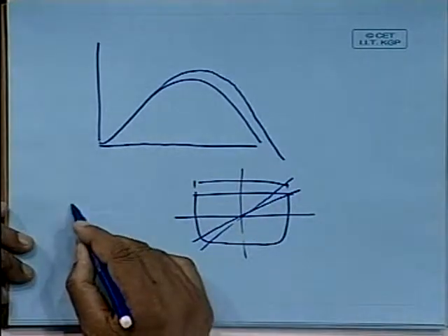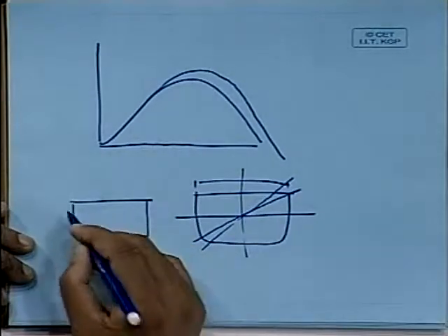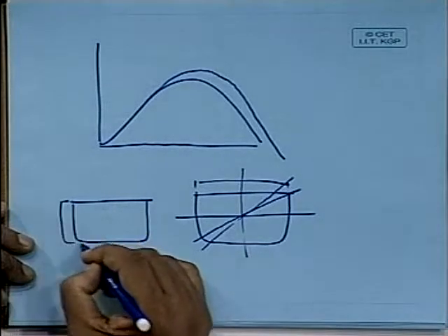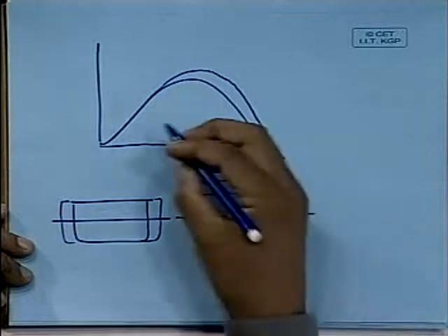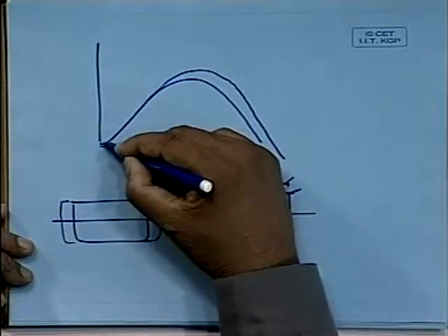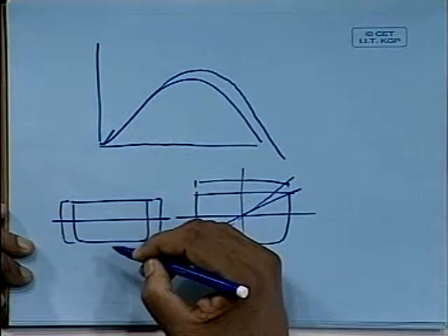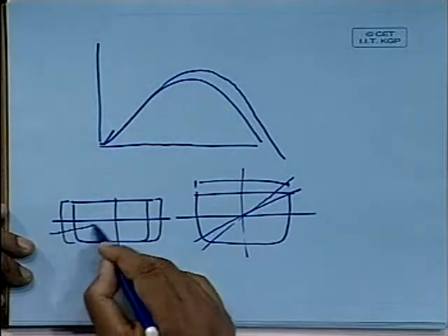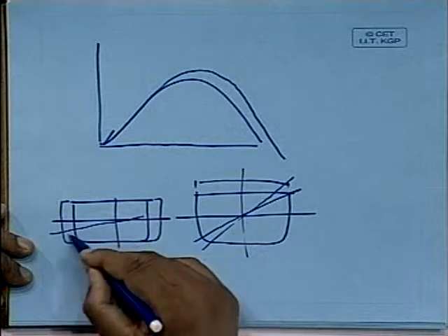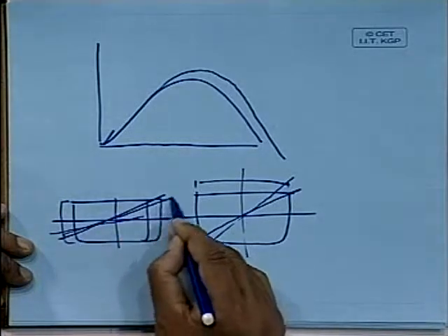Now if you increase the breadth of the vessel, then obviously I goes up, so the initial slope will become more because GM must go up. But on the other hand, the deck edge immersion, earlier it was at this angle, but now the deck edge immersion is at a smaller angle.